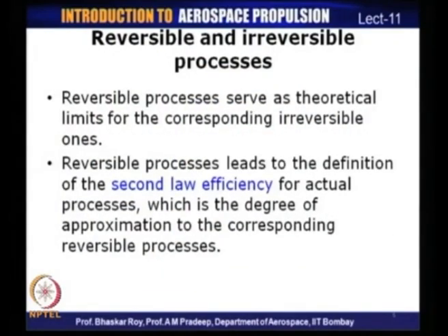And in this sense, the reversible processes will also serve as theoretical limits for the corresponding irreversible ones, which means that if, let us say, the irreversible cycle has a thermal efficiency of 30% or 40%, if the same process was to be carried out in a reversible manner, then the efficiency that you get from the reversible process will be the maximum efficiency limit that you can get for the corresponding irreversible process. So, you will obviously not be able to get an efficiency which is higher than what you get from a reversible process.